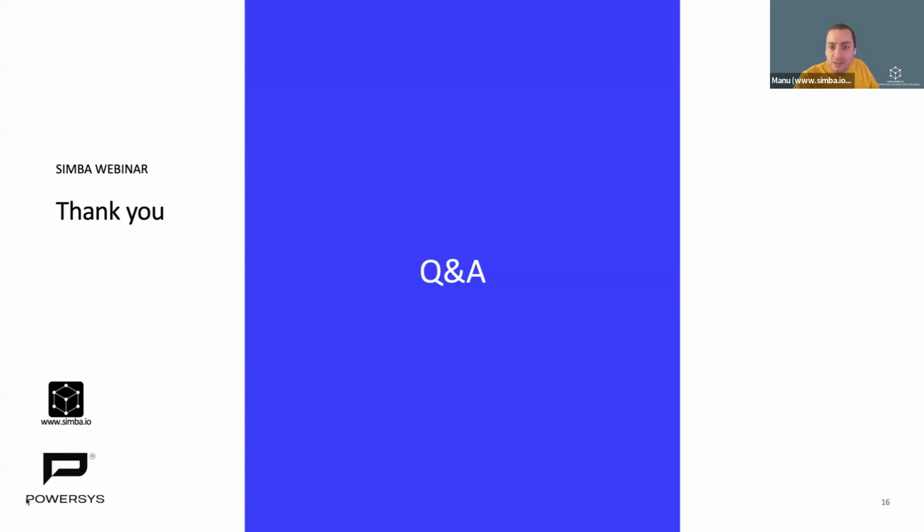Question from Sabir. How do the simulation results, like power loss, compare to the real life test data? Have you performed any hardware testing to back the simulation results? The answer is yes, but not directly. For instance, for the losses in the motor, JSOL, the company that developed JMAG and built the JMAG-RT, they have test benches. They have a lot of different motors, and they have validated the different types of losses of the model and the accuracy of the model.